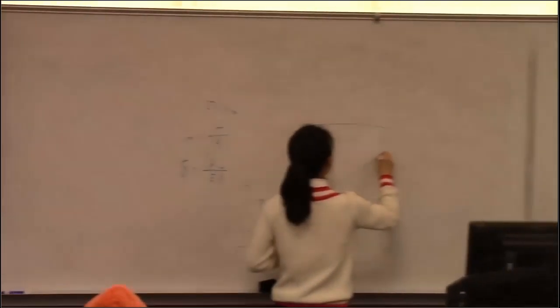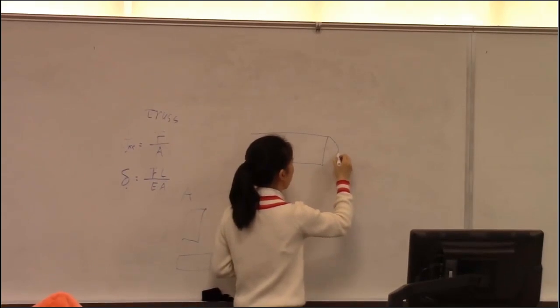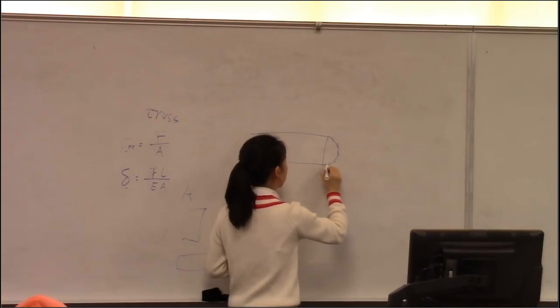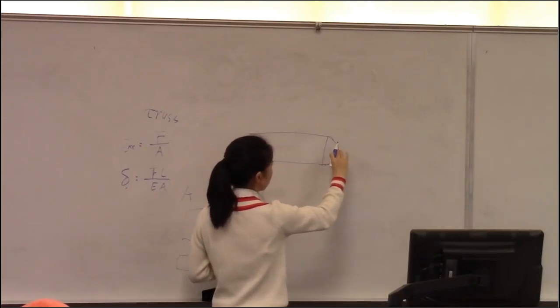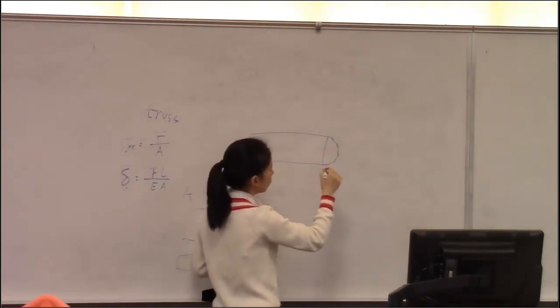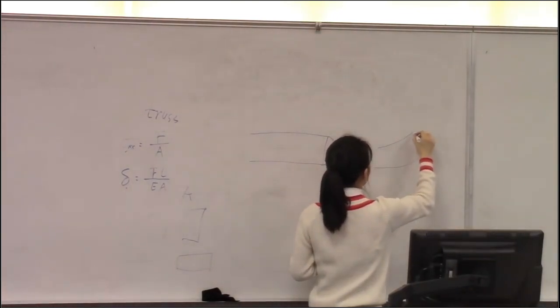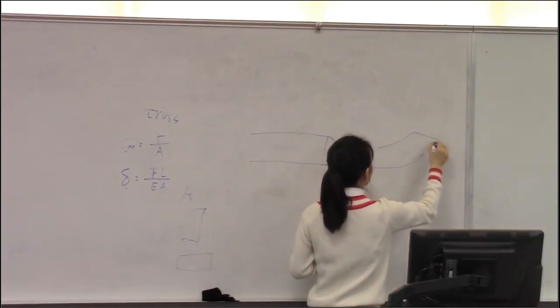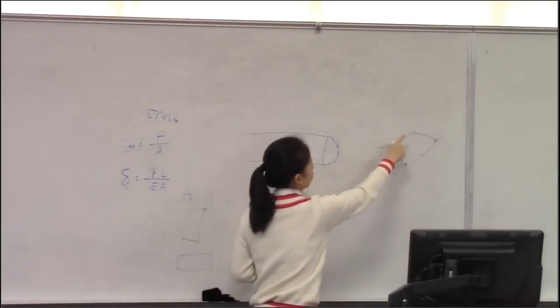Shear flexible means that if your beam is kind of thick, the shear stress is distributed in a way like this, right? This is what you learn from mechanics of materials. And because it's thick, this shear stress cannot be ignored. So when you bend, this shear stress will create a... what is the definition of shear strain? The change of angle, right? So this has shear strain here.